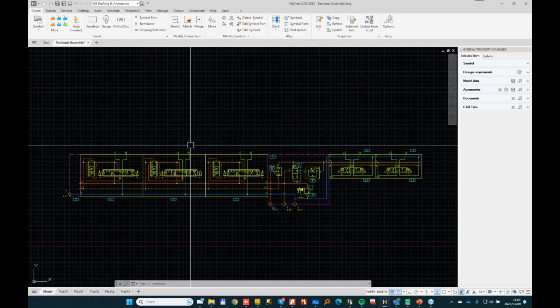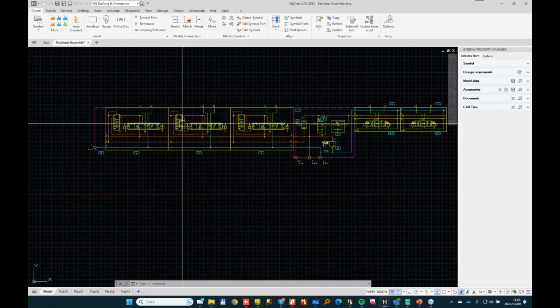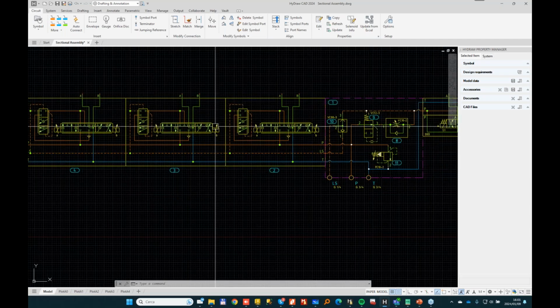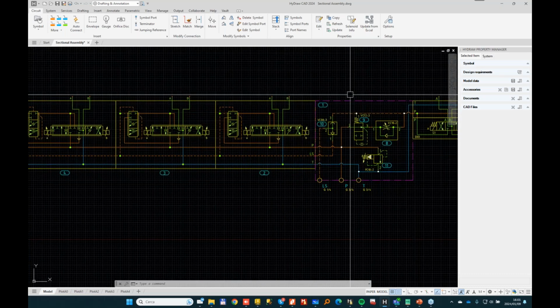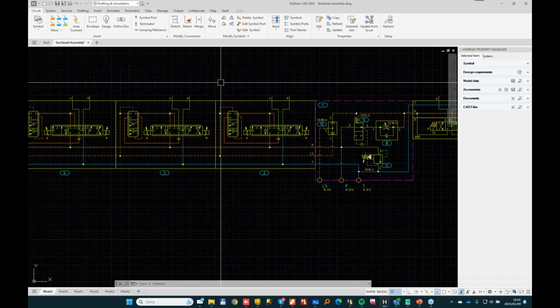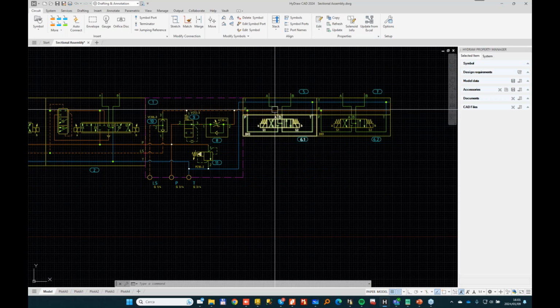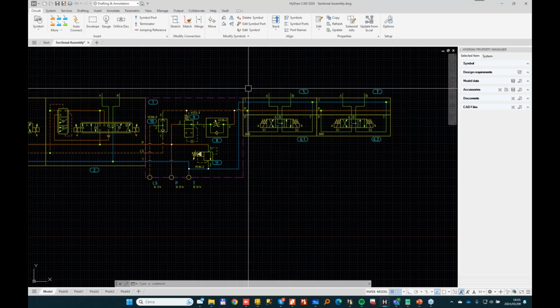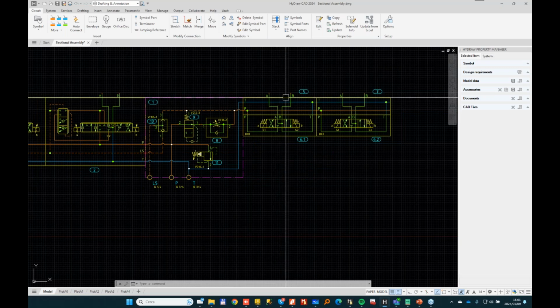So today I'll try to design a custom mid inlet for a sectional valve. Well, it's basically a mixed application. On the left, we'll have three compensated proportional working sections, and on the right we have a couple of modular NG6 subplates.